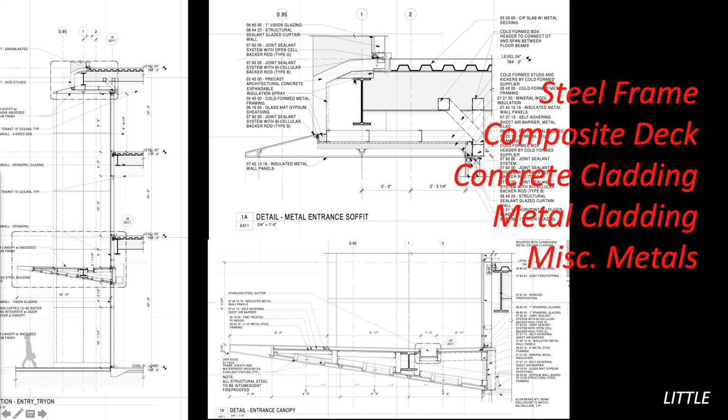One of them is that our steel is always going to need insulation and fire protection. So we have thermal insulation in part of this, but we also have almost a fire protection built in. In this particular project, there's a set of precast concrete covers that are really the expression of the building. So this is hidden inside of something else, which is doing the fire protection.